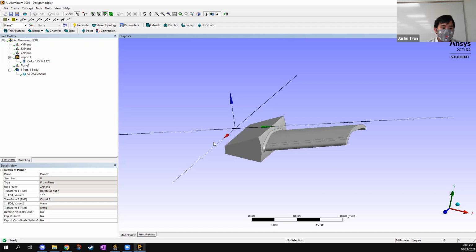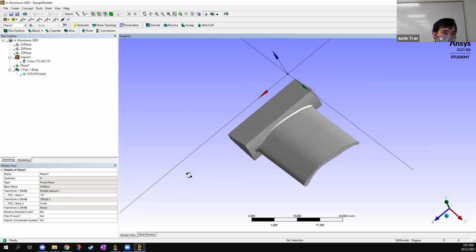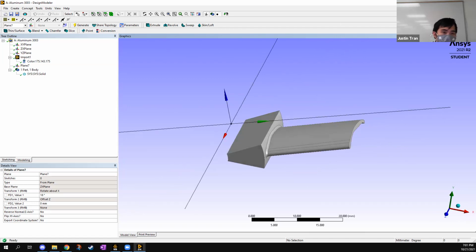The shape of this definitely induces a little bit of that lift and drag over the top. It would be interesting to see, if I was to simulate a high pressure or low pressure of that lift and drag, would that be more of a distributed load across it, where the lift would be from underneath, from the high pressure pushing up along that entire surface, right? Yep. So I would probably do it as a pressure differential. And so you'd have a lower pressure up top and a higher pressure on the bottom.